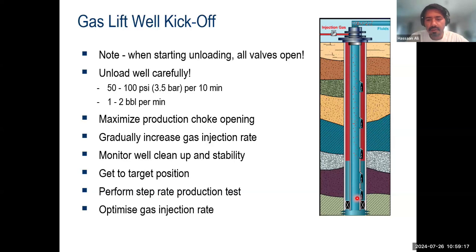There have been installations where there have been multilaterals. That means you will have a single bore, and then you will have multiple bores. Gas lifting in those wells is very challenging, and there are not a lot of wells like that. 95% of the wells are completed this way for the gas lift.